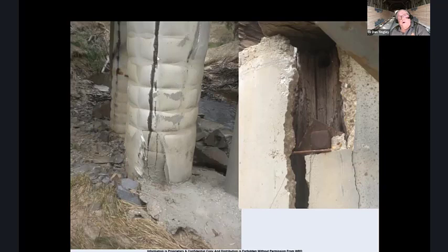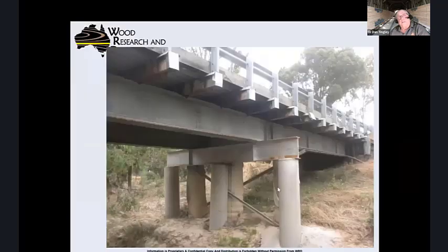Capillary action brings water up in the pile. It swells, bursts the concrete. He has to go back. Gee, I've got to fix this. This time he's gone back. He puts new concrete piles in place, and he puts web stiffeners in some locations and not in others. And he's still trying to fix the bridge. They're at $285,000 now, and the bridge still is settling.